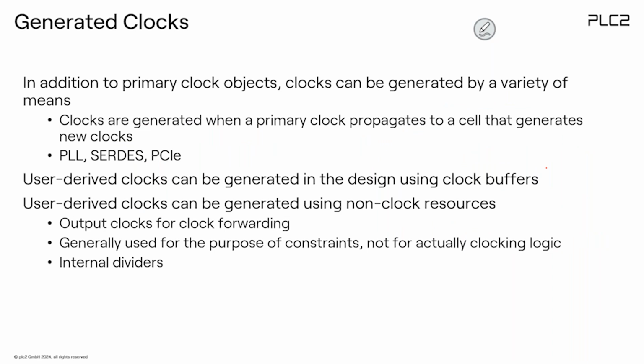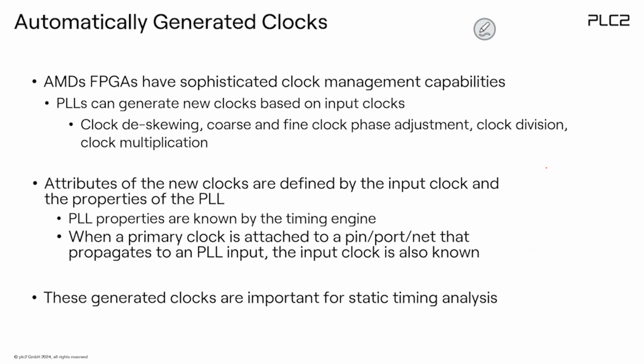This means we do have two different kinds of generated clocks. One is a so-called automatic generated clock. This means a situation where you define a clock, but Vivado completely understands what's going on and does everything for you fully automatically. It's called automatically generated clocks, okay? And the second type is the manual generated clock. In this case, Vivado is not able to understand what you are doing, even though it's correct, it simply does not understand, and you have to do something manually. It's called the generated clock. And we will see an example here. First, automatic generated clock means whenever you use, for example, a PLL to have an input clock and to define several output clocks, then all of the output clocks, including the phase, including the frequency, everything will be done and calculated fully automatically by Vivado, by this design suite.